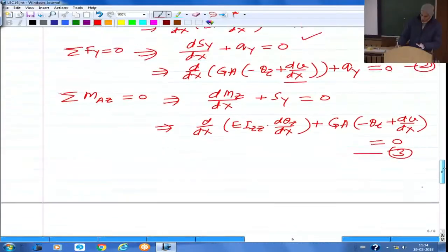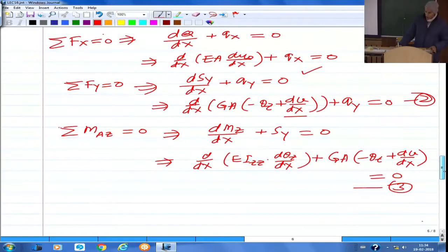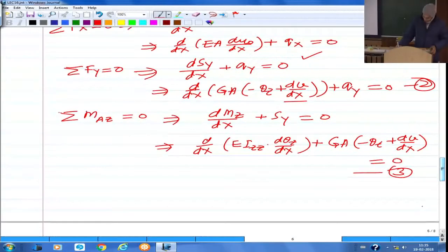And when we want to formulate the finite element for these, essentially we are trying to set up the element level governing equations for solving these 3 simultaneous equations. So the approach again would be, you can start with the weak form. You write the weak form for this, this, and this, and you can develop your element level governing equations, or you can go through the integral functional approach. Or from the weak form, you can actually get to the integral functional. I am giving the derivation of the integral functional from these differential equations as a home assignment, and this you should submit